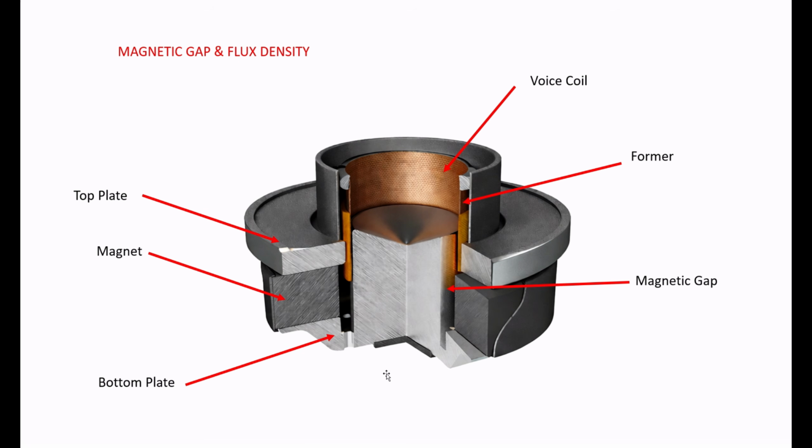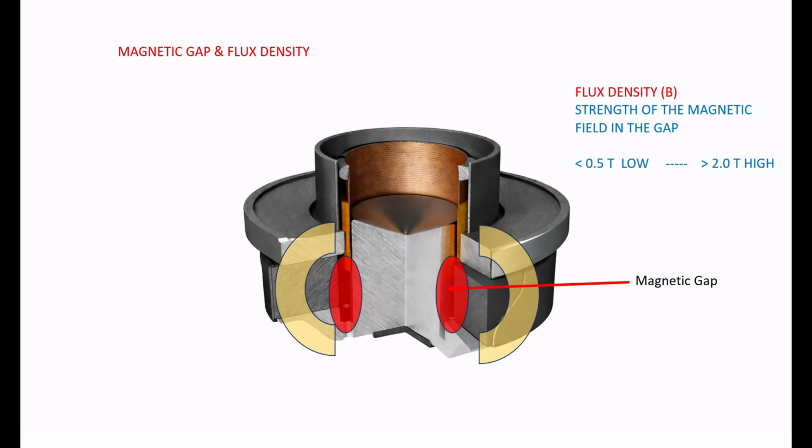And as we talked about earlier, the bottom pieces of the driver motor and the magnet form this magnetic circuit, and they're engineered to create a gap for the voice coil to slide up and down in. And it's this gap where the magnetism is most concentrated and provides the force that actually moves the voice coil and the interacting cone.